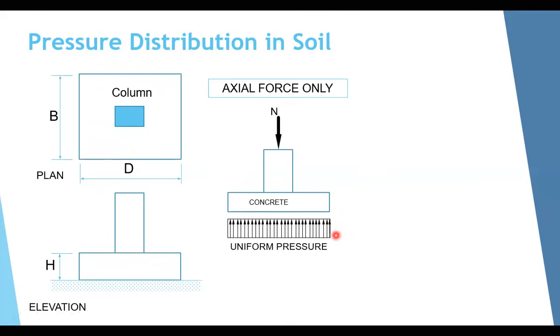So the stress, which we call P, the soil pressure, equals this force divided by the area of the footing. So it will be N divided by B times D. N over area.